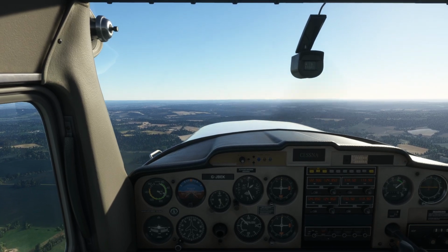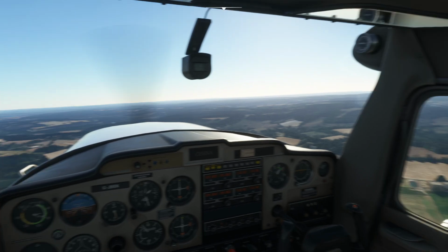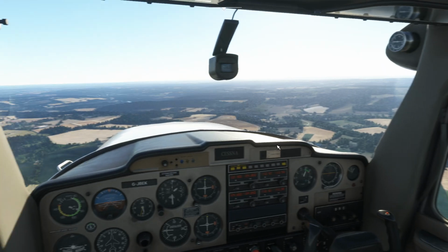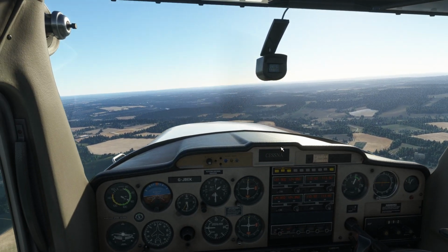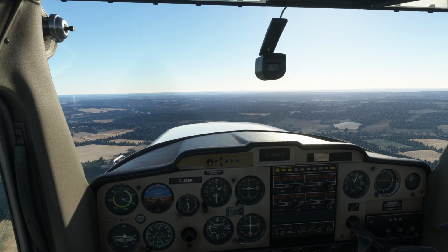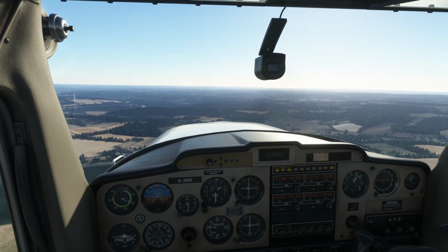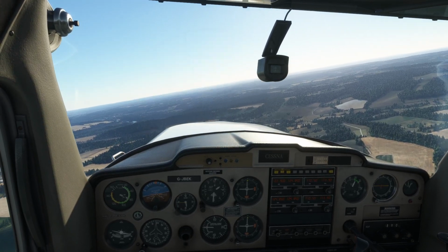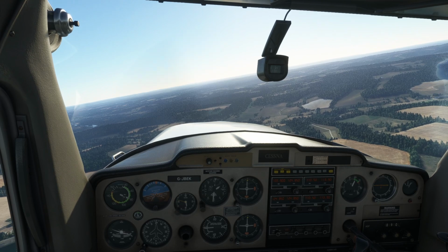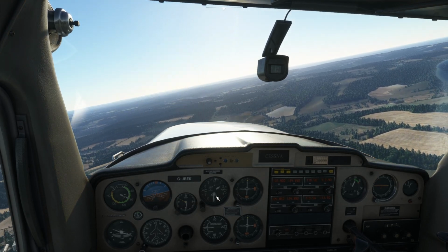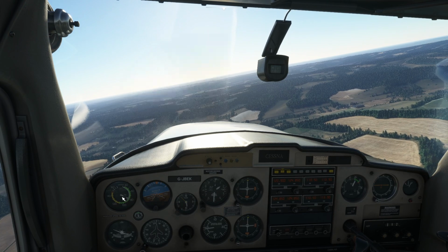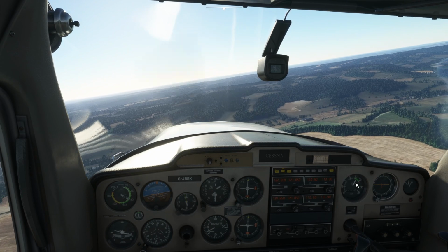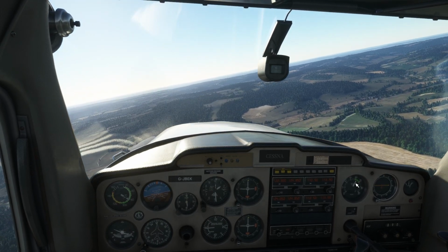Okay, so we're coming up to 1,500 feet, so we're going to cut the throttle back, look sideways. There's the town that we're looking to go around and the valley that we will turn up in a moment. Okay, we're just keeping an eye on everything, so we'll do the turn a little bit earlier this time. So the wing is on the marker, we're on the right altitude, we're good on the airspeed, we're a little bit low on the revs, let's open it up a little bit.